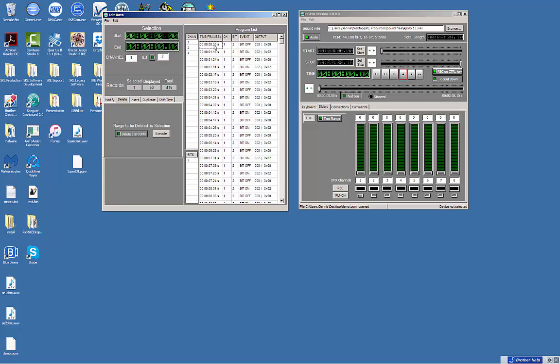You may not want to do that, however. You may want to retain the previous value that the bit was at and only modify it when the event occurs. In this case, we can delete that first bit frame, and I'll show you that. I'm going to select the first frame. I'm going to select execute, and it will remove that first event frame that sets it to 0. Now, whatever the bit ends at, that's where it will start at.